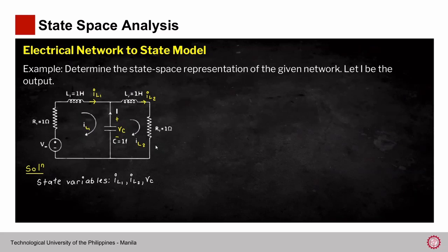In this particular circuit, only one differential equation can represent it, and only one transfer function can represent it. However, when we're talking about the state space representation, the state model, there are many possibilities. There are several possible state models that can represent the same system. The state space representation is not unique, so there are many possible answers.